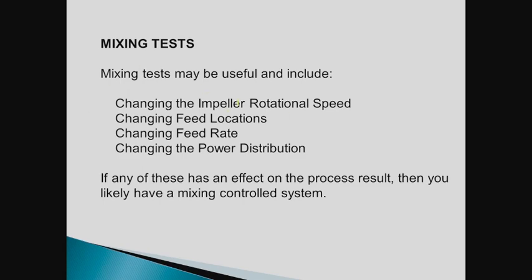Well, change the impeller rotational speed. You can change mixing locations, or feed locations. You can also change feed rate, because whenever you're feeding something, you have jet mixing. And the jet mixing may actually become very important. And of course, you have your old buddy, power distribution in the tank.